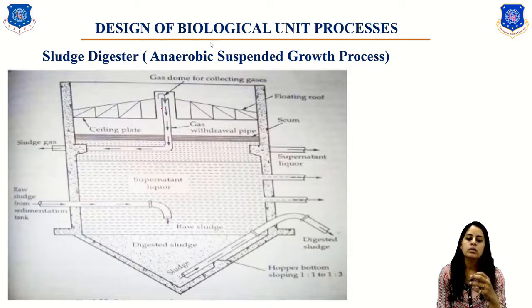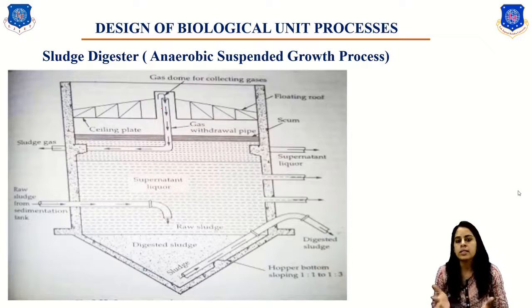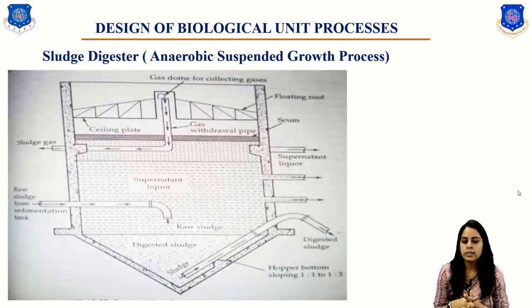The bacteria carry out the degradation first and form intermediate products of volatile acid, and then methane forming bacteria convert the acid into carbon dioxide and methane, right? The low molecular weight fatty acids are the intermediate products of anaerobic biodegradation, and these acids are known as volatile acids, because they can be distilled at atmospheric pressure.